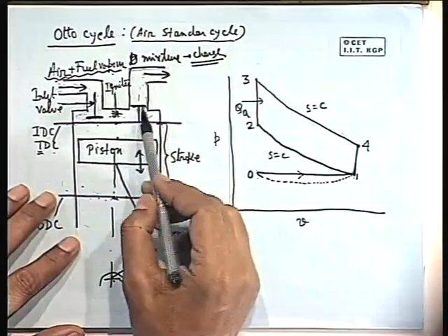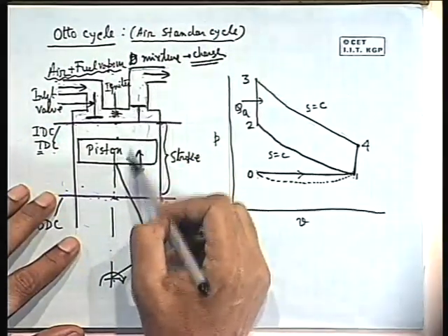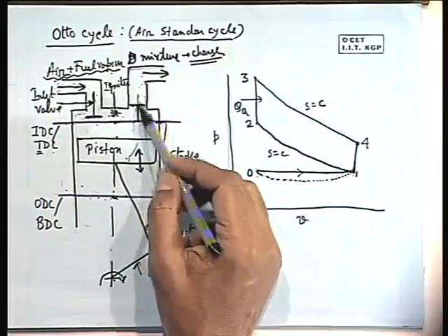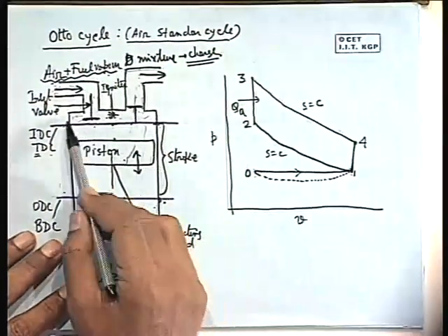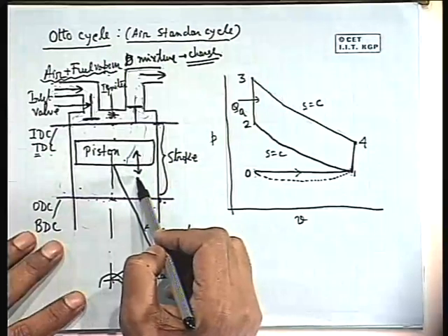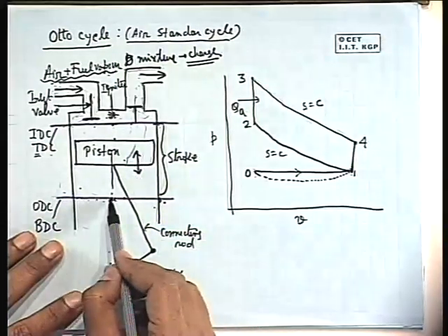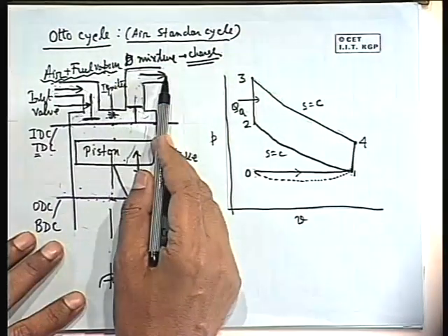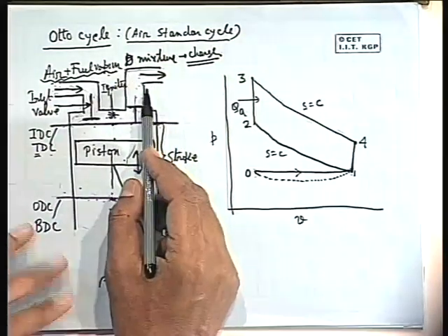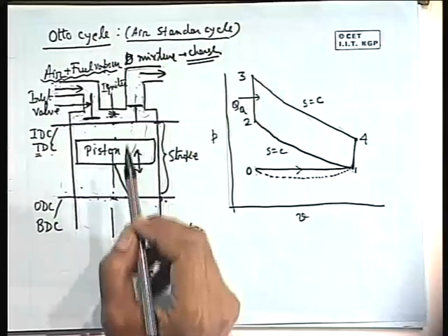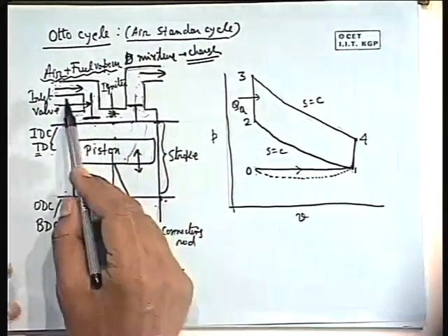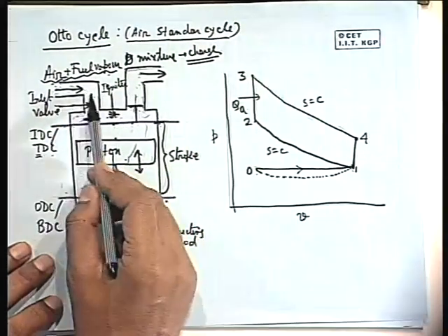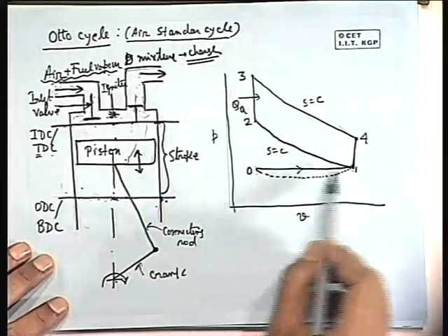That means pressure equalization. You make the valve open, this pressure difference causes the air to flow. So immediately the pressure equalization takes place. The air here is at atmospheric pressure, and then the piston moves upward to push the remaining part of the air going out of this exit manifold or outlet manifold. Now this happens in a similar way, simulated in the similar way as the suction stroke or the induction stroke, at constant atmospheric pressure.